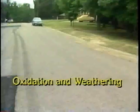Oxidized and weathered pavement surfaces. Pavement surfaces become oxidized and weathered with age. As pavements age, the asphalt in the surface is oxidized, resulting in a brittle condition and loss of aggregate. The surface aggregate may also become worn and polished over time due to traffic wear and weathering.